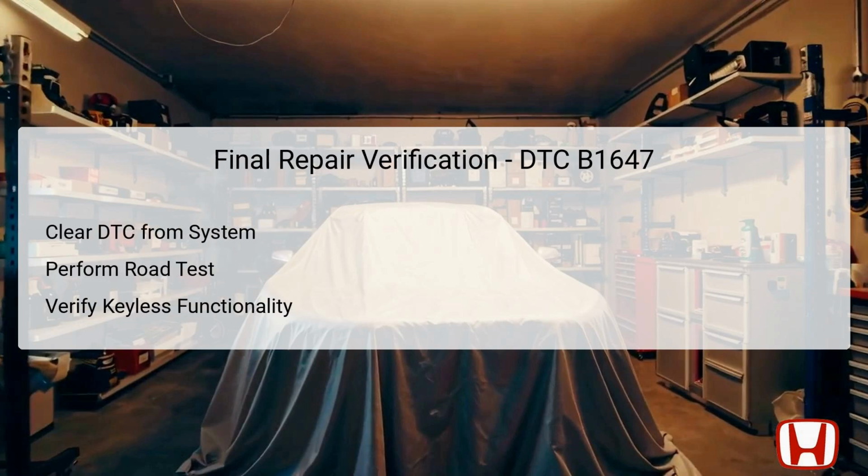Once all relevant repairs have been made and components replaced as necessary, it's crucial to perform a final repair verification to ensure that the issue causing DTC B1647 has been resolved. Start by clearing the DTC from the system using the HDS tool. Then turn the ignition off and restart the vehicle.